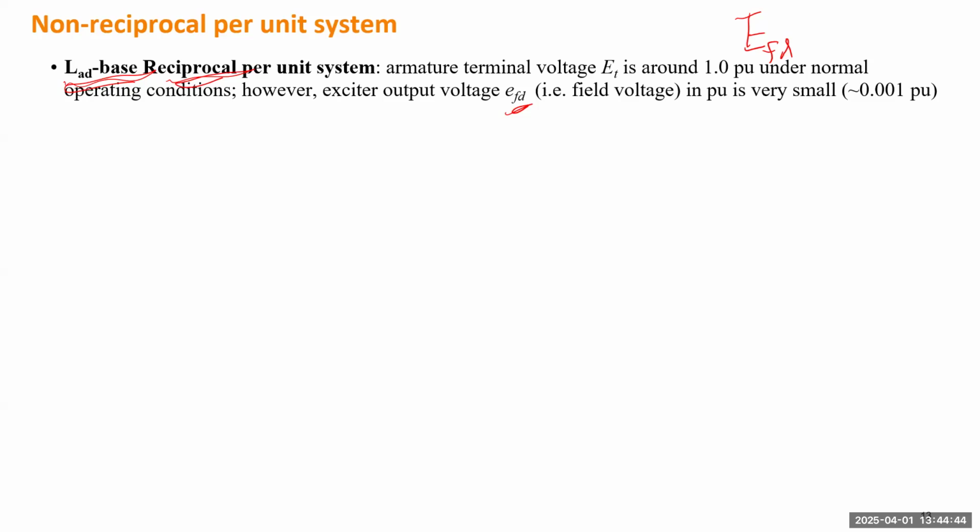You want to keep all the computation away from that precision level. For example, if you use MATLAB, the precision level may be 10 to the negative 16 or 24 or 32, I don't know, but it's a very small number. But you deal with a lot of generator variables whose actual per unit values are very small. That increases error at each numerical step. So you want to translate every variable into a range near 1. That would be ideal.